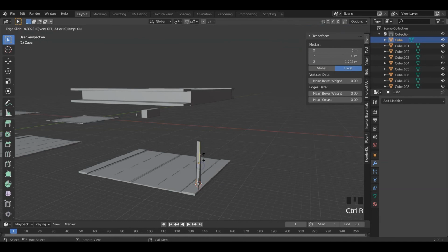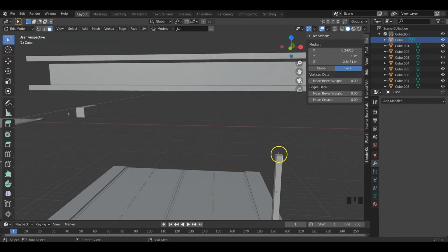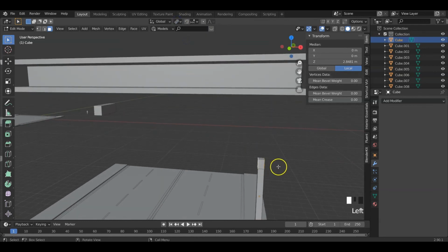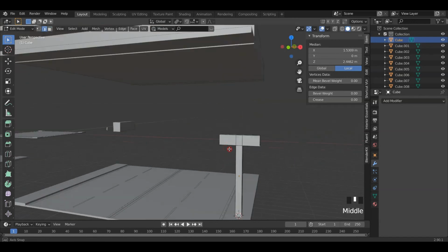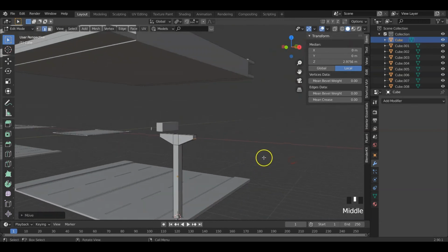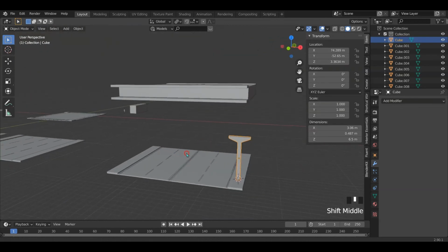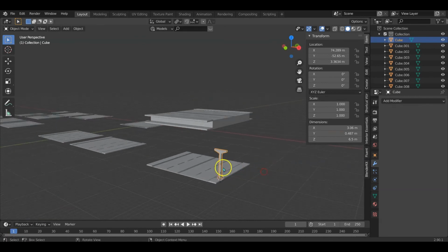Well, the height or the clearance, as to say, should be about 6 to 6.5 meters. That means we'll be bringing the bridge down. Remember, we'll be keeping things to scale as much as we can. Generally a truck, lorry or a bus, buses are generally 3.5 to 4 meters of height. Of course, there are trailers that might go about 5 meters height, maybe. Therefore, generally 5.5 meters is the standard. I'm just going in for safety, 6.5 meters.